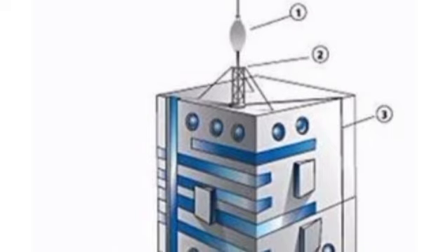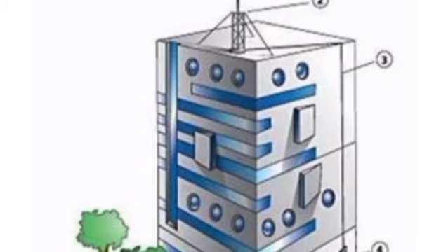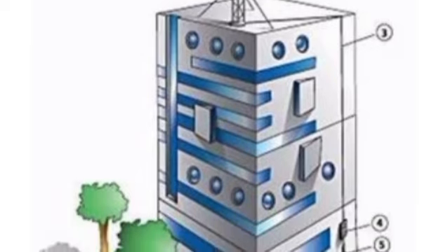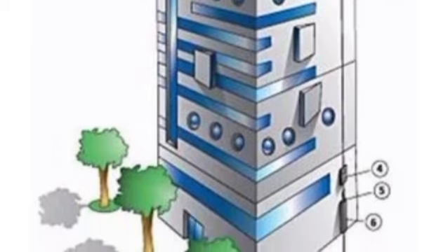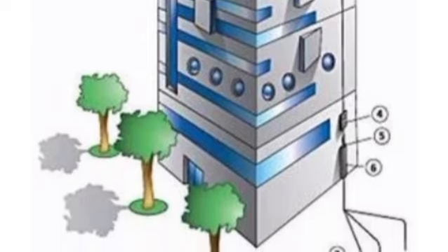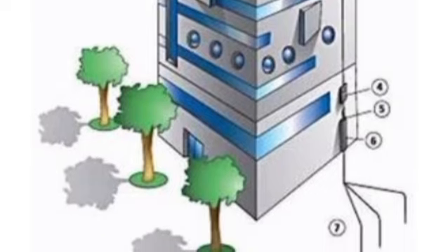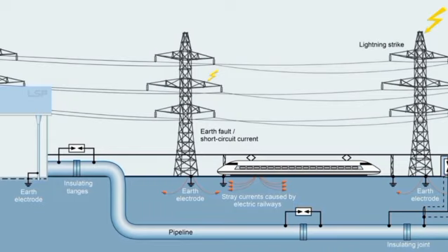Usage. Lightning arresters are primarily used in power stations, power lines, distribution stations, power generation, capacitors, motors, transformers, neutral points, steel making, and railways. Surge protectors are mainly used in low voltage distribution, cabinets, low voltage appliances, communication, signal, workstations, and server rooms. Conclusion. The nominal discharge current, In, is an important parameter for both surge protectors and lightning arresters.